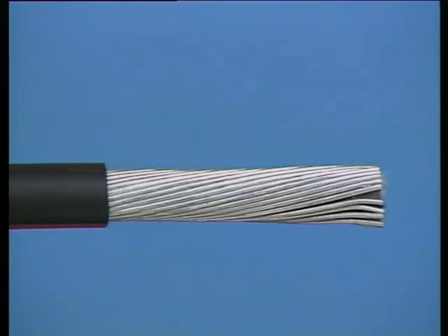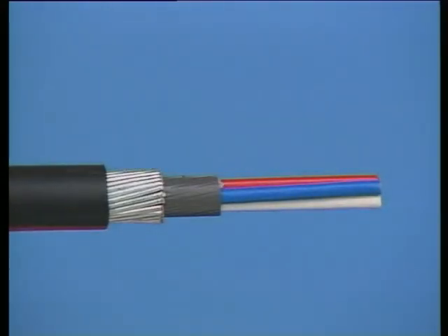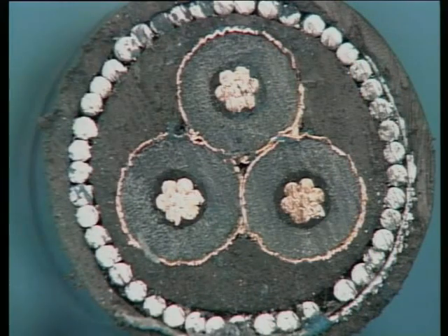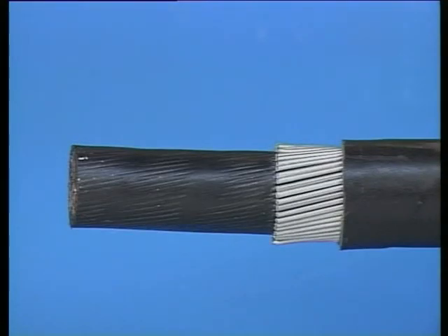Beneath the armoring layer is the bedding layer, which encases the conductors in this cable type. Each core, within or beneath the bedding, is itself insulated either with PVC, as in this example, or with XLPE material. Let's turn our attention briefly to a typical XLPE insulated cable for purposes of examining certain extra features.